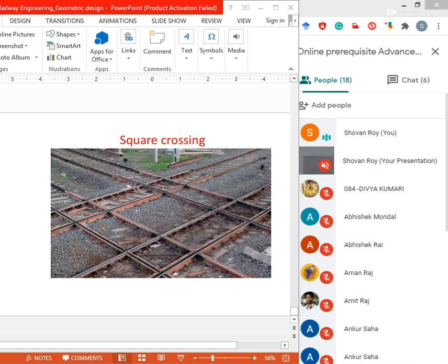An adequate number of platforms should be provided so that all trains can be dealt with at the same time. There should be convenient sidings where extra carriages can be stabled after having been detached from trains or before their attachment to trains.